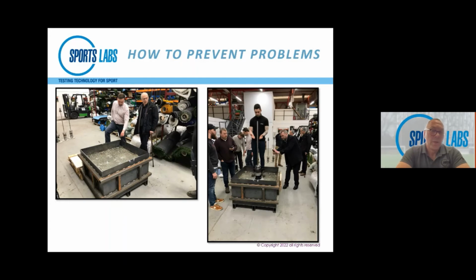density that's required to make it perform properly. This way we can start to look at what happens on a site, and we can look at the tools we use, like the various testing equipment Mark's highlighted, and you can see on the right hand side we're testing for compaction, for stiffness in the mould, and the mould's big enough to take out all the edge effects, so we're not restraining the material artificially, because it's literally tons of material that we're looking at in that mould. So that's one of the things we can do.